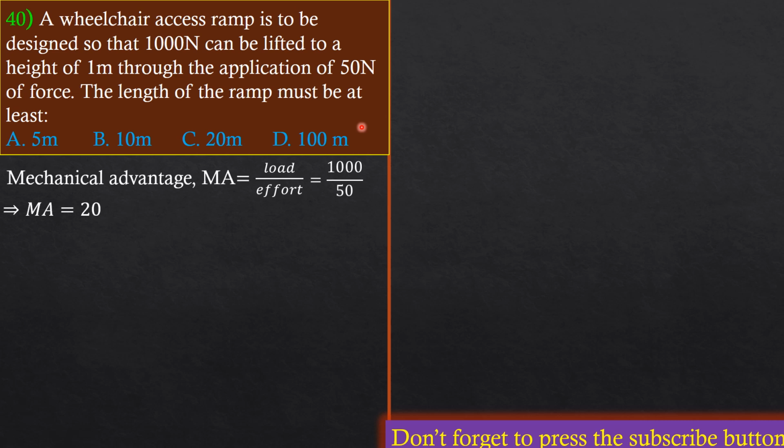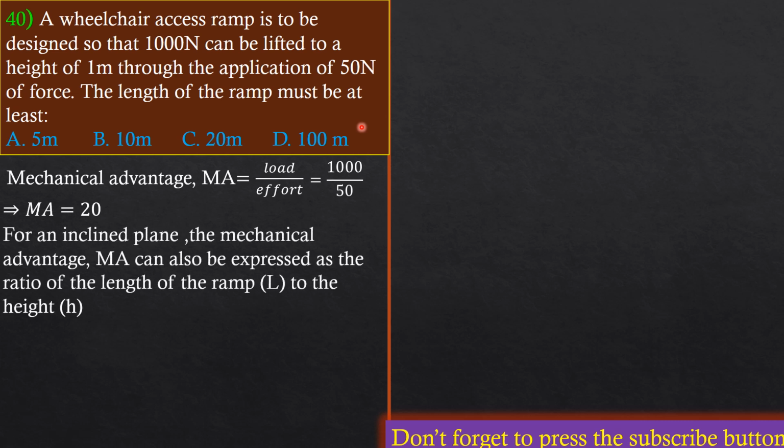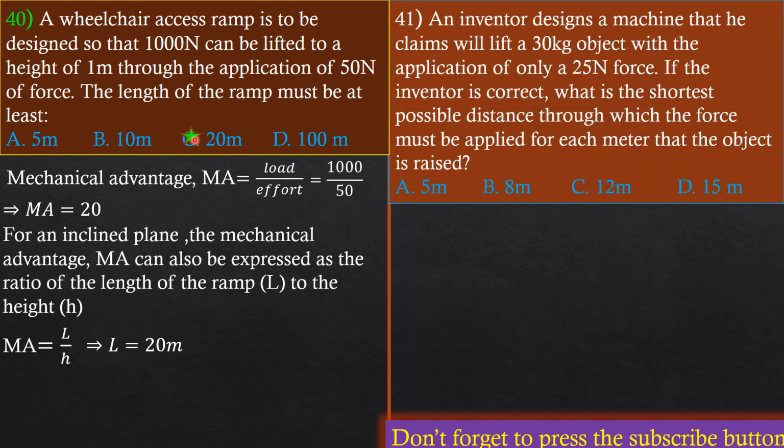Now, guys, for an inclined plane, the mechanical advantage can be expressed by simply taking the ratio of its length to the height. It therefore means that the length in this case, since the height has been given as 1 meter, is just equal to 20 meters. Great. So option C has to be the best option.